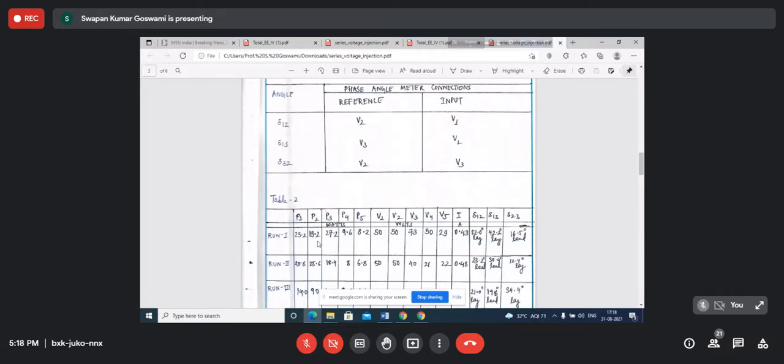In an actual transmission line, obviously, the power will be of much higher magnitude. Okay. So, you see that in run one, the purpose was to transfer power from N2 to N1. Okay, 2 to 1. So, 1 should lag. Delta 12 is lagging by 22 degrees. So 1 is lagging 2 by 22 degrees. Okay, D1 is lagging by 22 degrees.